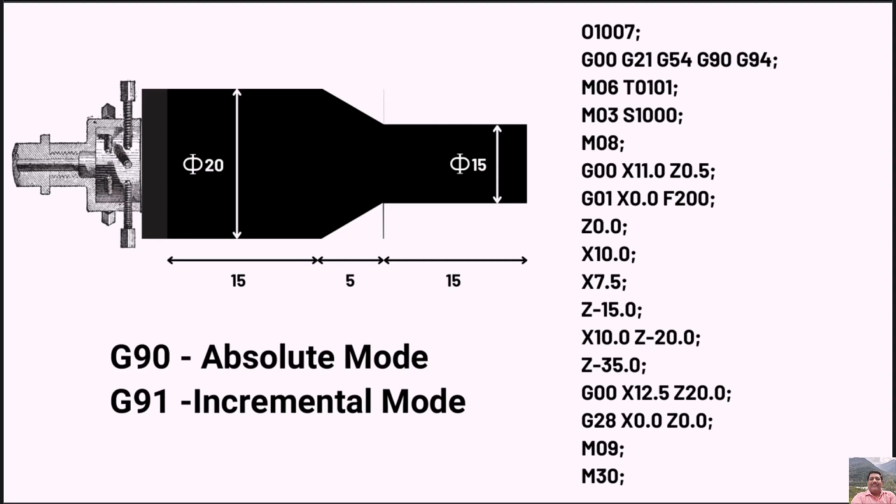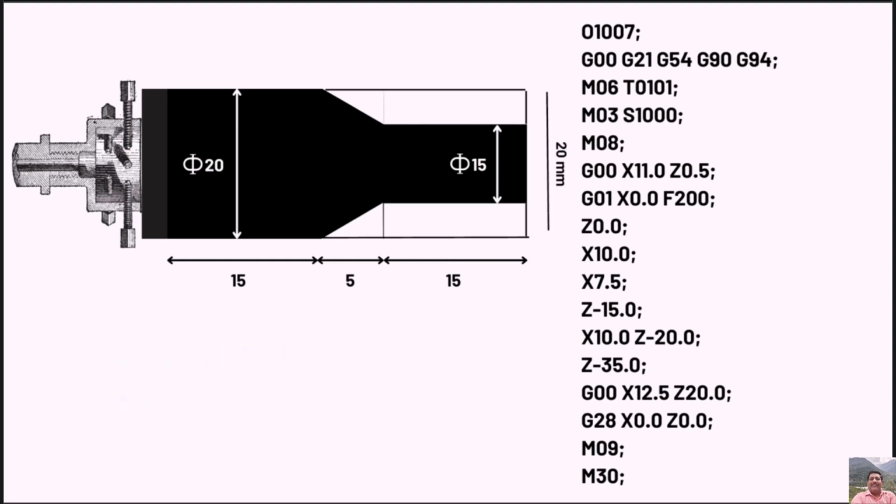We will discuss this later in the lecture, but first we need to define the size of the workpiece to undergo operation. In this case, we will need a circular bar of diameter 20 mm. This would be our workpiece. Now here we have to define a datum position from which the tool will start moving. So this point here is considered as datum and the tool will be moving from this point O to 1 to point number 3 and point number 4.